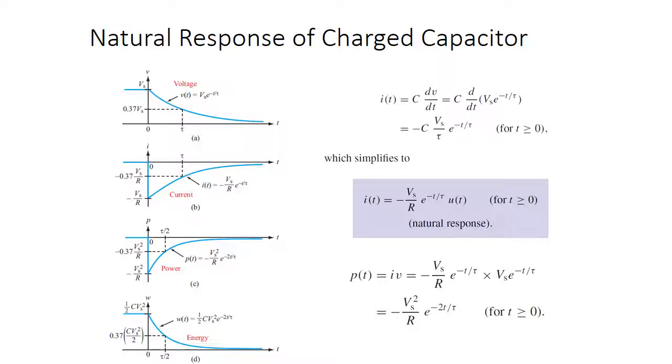If we look at all the way up to 0, this is a graph of the voltage. All the way to 0, your voltage is whatever your source is. Because remember, if you have a 9-volt source, you have an open circuit at the other side where the capacitor is. So it's always going to be 9 volts at the top. You have nothing removing, and no current is flowing through that capacitor, so it just stays 9 volts. But as soon as you switch that switch at time equals 0, you're going to start slowly draining that capacitor, and the voltage is going to start slowly decreasing.